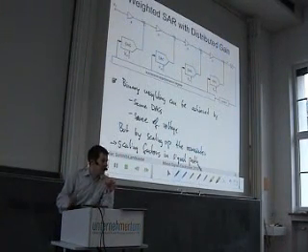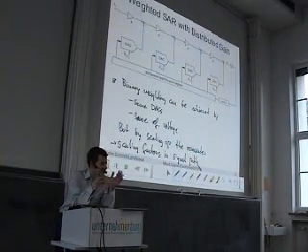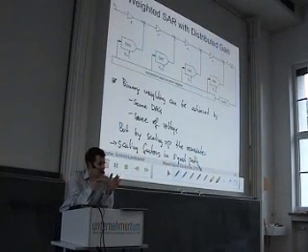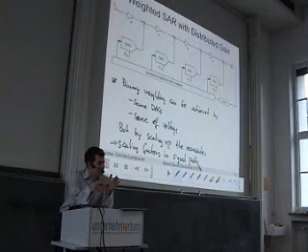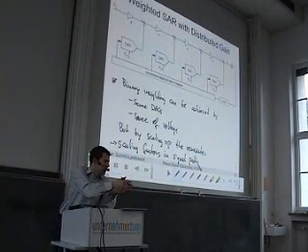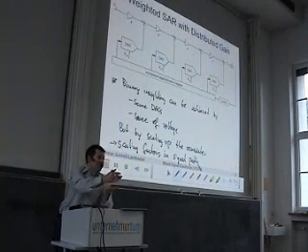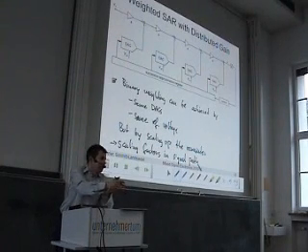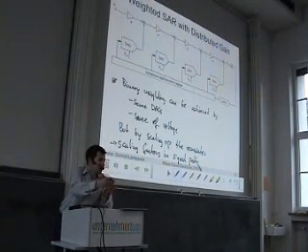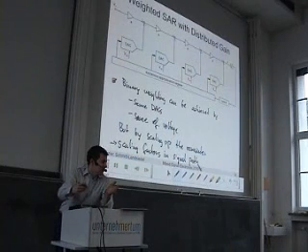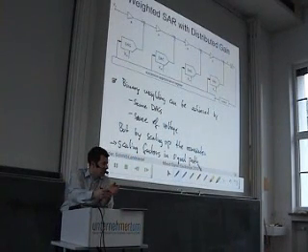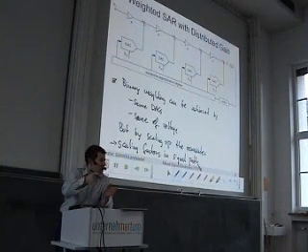Sorry, what we did so far is that we took a signal and added or subtracted something which was reduced in each cycle. So we started with 1/2 times the reference voltage, then in the next step we had 1/4 times the reference voltage, and these increments got smaller and smaller. What we have now is that we take the remainder, we do not reduce it, but we scale it up.